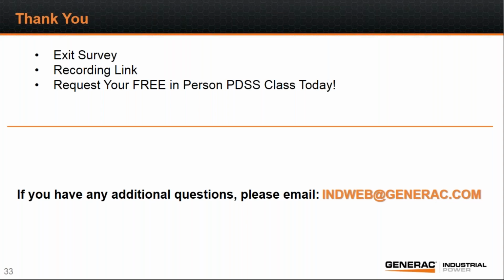Yeah, you're trying to get the harmonic distortion down under 12%. That can be done with a filtered 6 pulse, it can be done with a 12 pulse, or it can be done with IGBT input. So anything that brings your harmonic current distortion under 12% usually takes care of the problem. So any of those options will work for you.